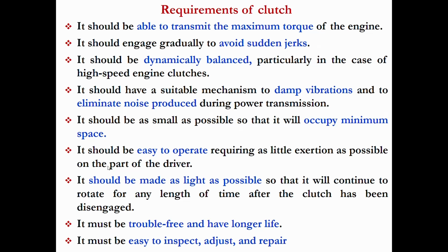The parts of the clutch must be dynamically balanced, otherwise it will undergo failure, since the inner parts of the clutch assembly rotate at higher speed. So if there is an imbalanced situation, or if some of the parts of the clutch assembly are not properly balanced, that will undergo failure. Then the parts of the clutch must damp vibration, so it should not create any noise while engaging and disengaging the power transmission.